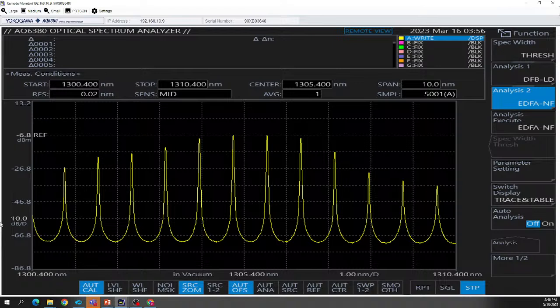And then for actual, like, when that calibration fails, you'd want to send it in for, let's say, NIST calibration, where they test different wavelengths instead of just one wavelength that the internal calibration does. And that will essentially put your OSA back into calibration, since there is a limit of what the internal calibration can do.